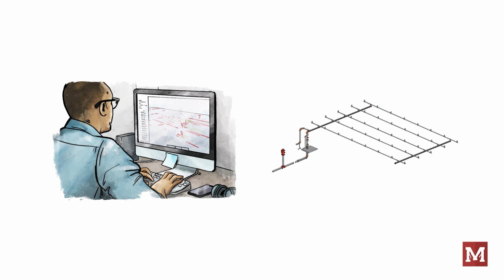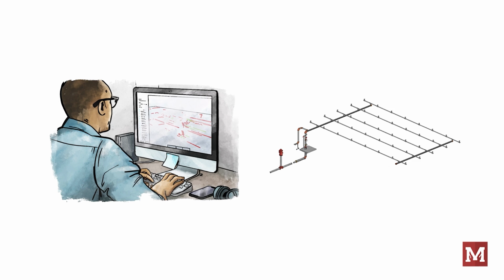This requires an assessment of pressure loss due to friction in the pipe network, as well as pressure required due to elevation changes. In some cases, buildings that incorporate standpipe systems may require outlets on the roof itself. These are considered within NFPA 14.